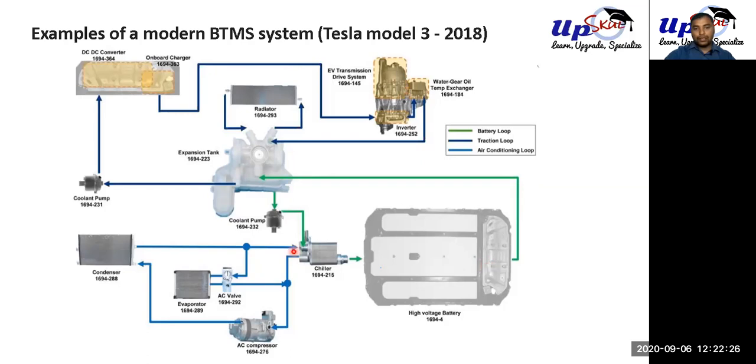So coolant is going out, being cooled down in the radiator, and then it's coming back through the chiller. There is sometimes a bypass connection also to bypass the chiller when it is not required. Because this is the common air conditioning system that is also providing comfort to the passengers, you cannot turn off this one, but you can just bypass the chiller connection.